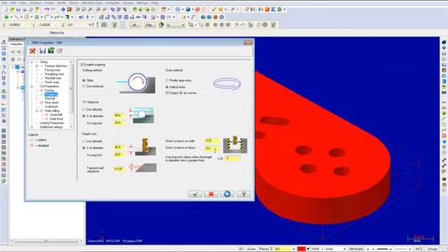You can now select the Rest Mill page. This page allows you to add Rest Mill toolpaths to the FBM Mill operation and to define their cutting passes. Mastercam creates the Rest Mill toolpaths after roughing operations and before finish passes. Rest Mill toolpaths are roughing operations that remove remaining stock based on a previous roughing toolpath or based on a roughing tool. Make the following changes as shown.